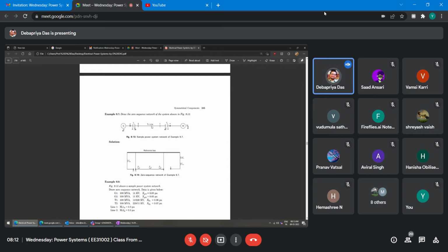For example, you draw that. That's why you will find that in all the examples I have given, it is the zero sequence diagram. Data and other things will be seen later. For example, this is a generator. It is star grounded. This is a motor. It is also star grounded. Here there is no ground reactance or impedance. Here, for the motor, one ground reactance is there, and this is delta star grounded, and this is star grounded delta. This is a transformer.